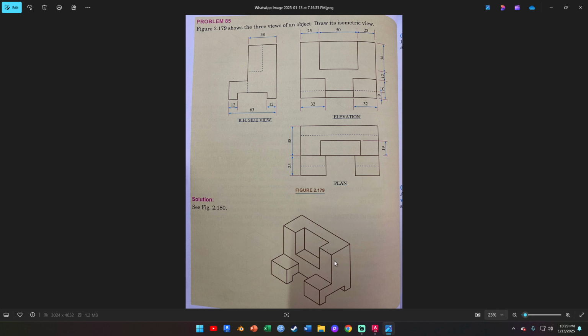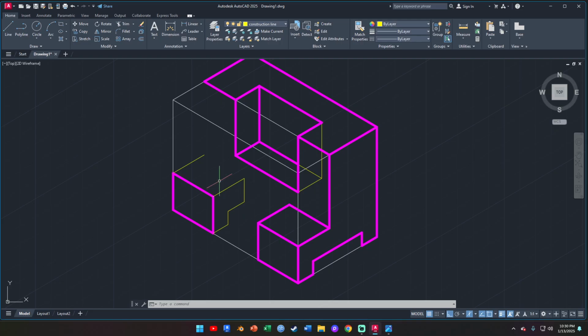And we know that this line goes into the same 25 mm length, so you would need to switch the isoplane left since that line is on the left, and you simply just extend out the line any measurement, right, once it passes here. So it doesn't really matter how much it passes. If you want to, you could just trim out the extra, right?